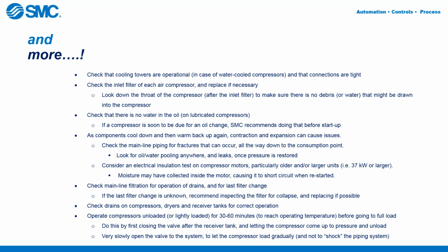I talked to one veteran troubleshooter, and he said they noticed just in the nick of time that there were about 10 gallons of water sitting in the throat between the inlet filter and the compressor inlet intake. And that would be disastrous, right? A compressor is meant for compressing air. Water doesn't compress. So drawing even a gallon of water into a compressor would have catastrophic effects.